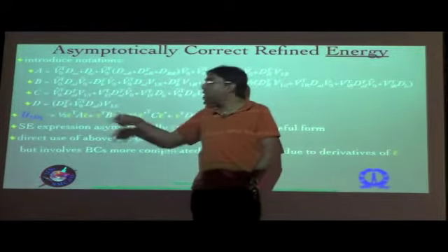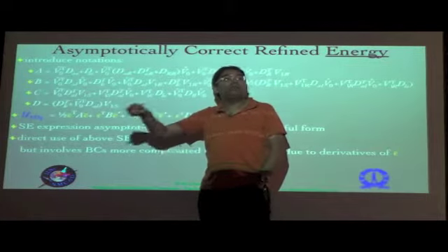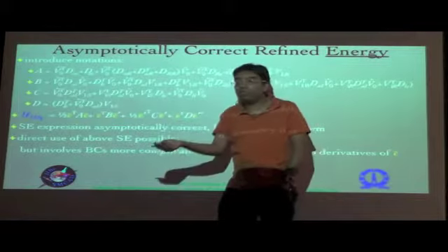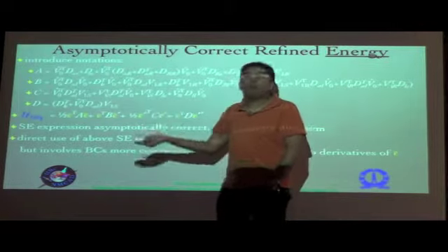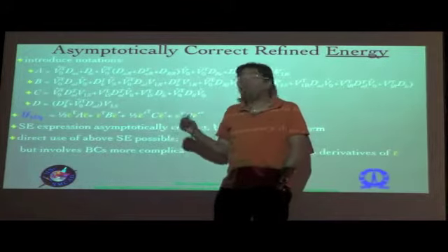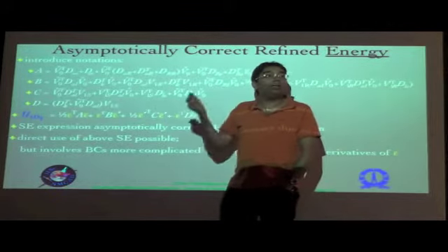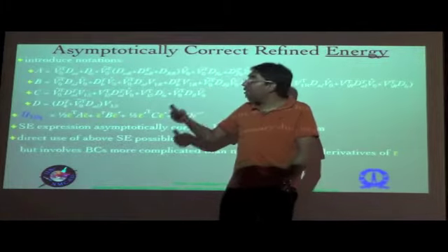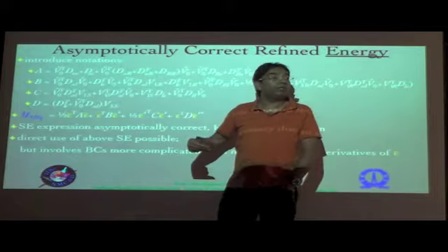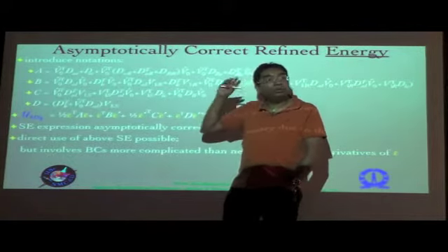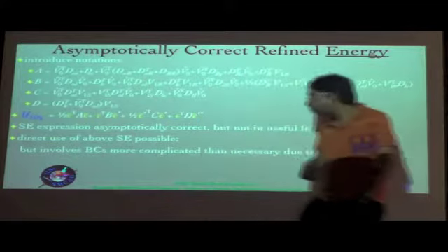Remember that epsilon bar is defined as epsilon subject to 2 gamma 1 alpha equal to 0. In other words, the transverse shear deformation information is contained within the warping rather than as a 1D variable, because it is in reality not a degree of freedom. Even when you introduce 2 gamma 1 alpha, it is an artificial degree of freedom that you are trying to introduce just to force your asymptotically correct solution to be in that particular form.